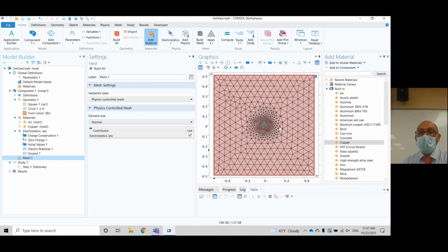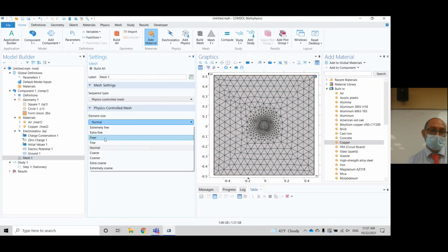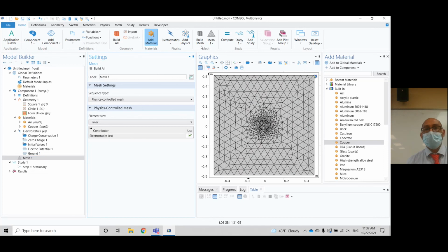And it's going to solve one triangle at a time. And then the output of this triangle is going to be the input of the triangles around it. And it just goes by that. Just do one triangle and then the neighbors, and then keep going, keep going, keep going. The more triangles, the finer your mesh is, the better your result. But also, the more intense the computation is going to be.